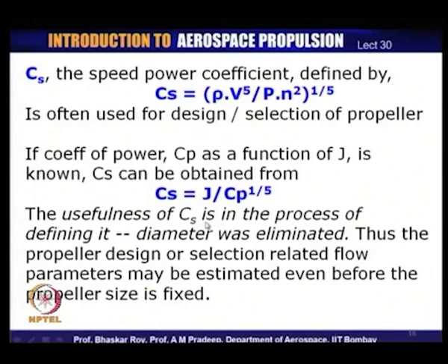This is because in the process of creating this definition, the diameter of the propeller has been eliminated, as a result of which you have a normalized parameter, in which the size of the propeller has been taken out of the equation, and as a result you can create a propeller characteristics conceptually without to begin with a priori bothering about the size of the propeller, which can be then factored in a little later in the design process.